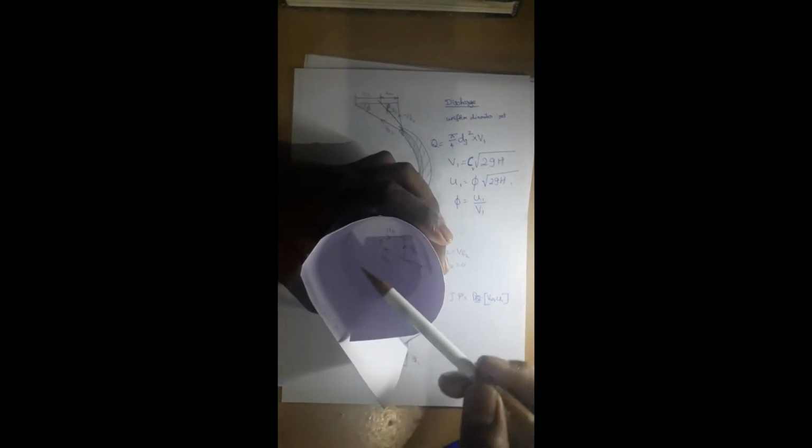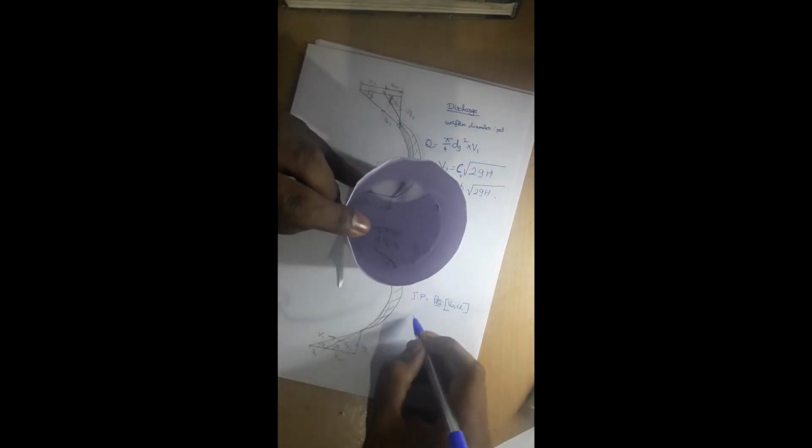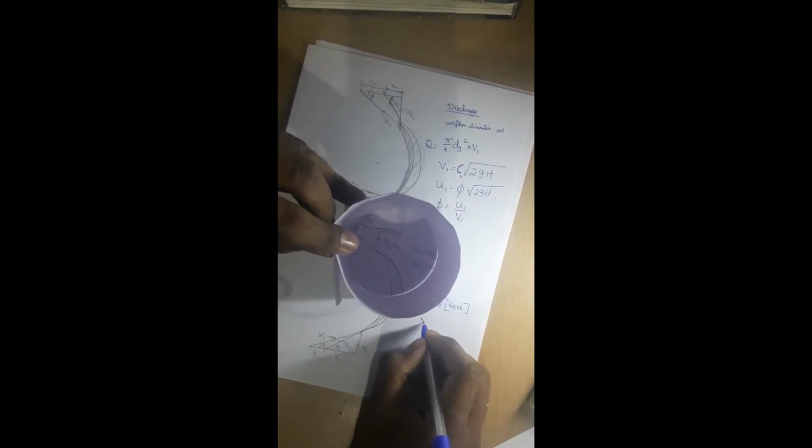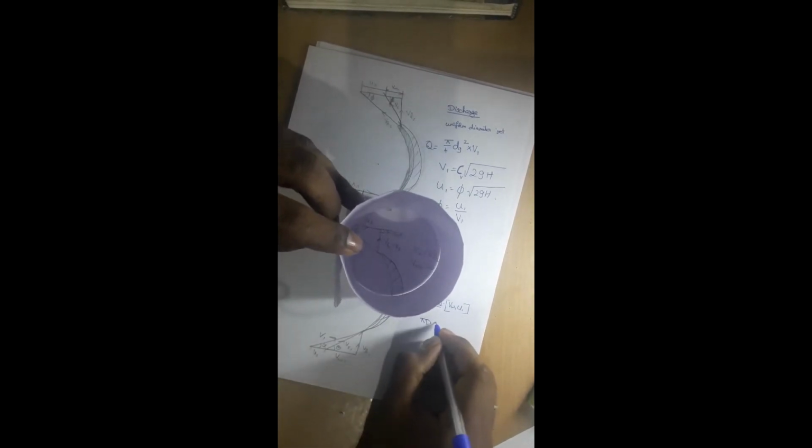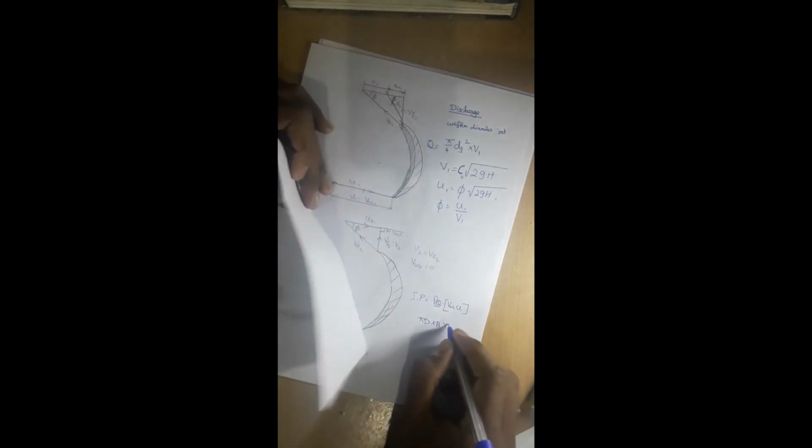Here the water will be coming in the axial direction and flows to the center and moves out like this. So water comes here, goes to the center and moves out. So in this case, the circumference of the blade, pi d, is the inlet condition. So area of flow is pi d, and the thickness is to be considered, the blade thickness, pi d into b into,